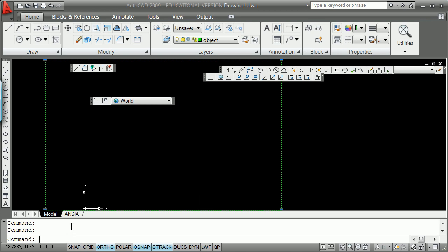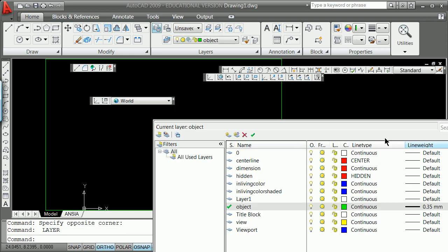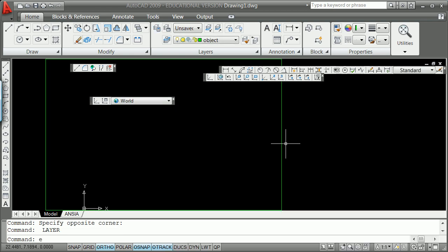Alright, so the concept is to draft the structure, then eventually draft a star free body diagram if you have a concurrent force problem. That means that everything emanates from one point. So if something is pulling on it, it's fine. If something is pushing on it, you have to transmit it through the structure so you can catch the direction. That's going to be true whether you're doing it by algebra or trig, or whether you're doing it by, try one more time.